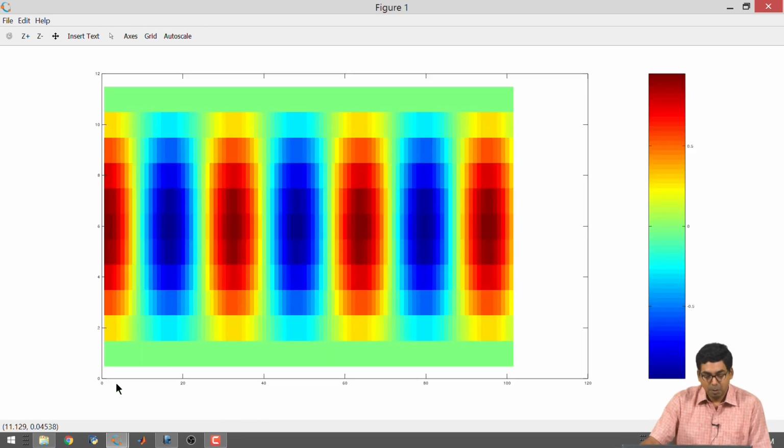All right. So, now this is your z direction, all right, and we are plotting for a slice. So, this is your x direction going here, right. We have picked up m equal to 1, okay. It is saying that if you pick up m equal to 1, and n equal to 1 is what we have picked up, and we have taken a slice right in the middle of the waveguide. M equal to 1 is telling you that you are going to be having a spot in the middle of the waveguide, all right. And along the z direction, it is a travelling wave.